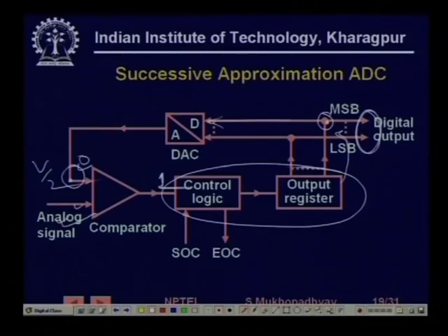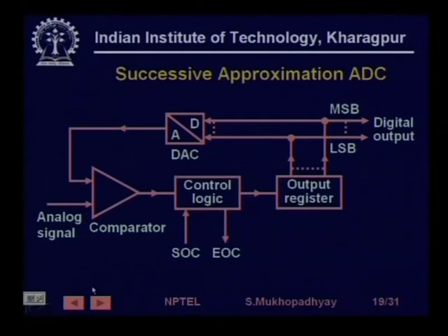So that is how you compare it with a number of digital numbers till it exceeds, and at that point you stop. So when you stop, you get a set of digital bits which is closest to this analog signal, right. So this is how a typical successive approximation converter works, and this is just one way.